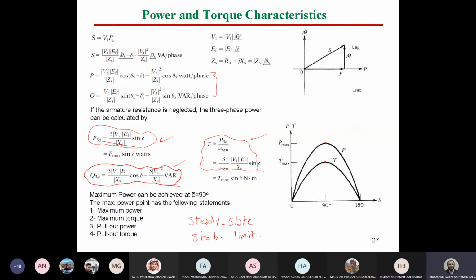What do you think? High current. It should be high current. So what about the conductors? The machine conductors itself, the windings. In order to carry high current, you need high cross-section area, large diameter.